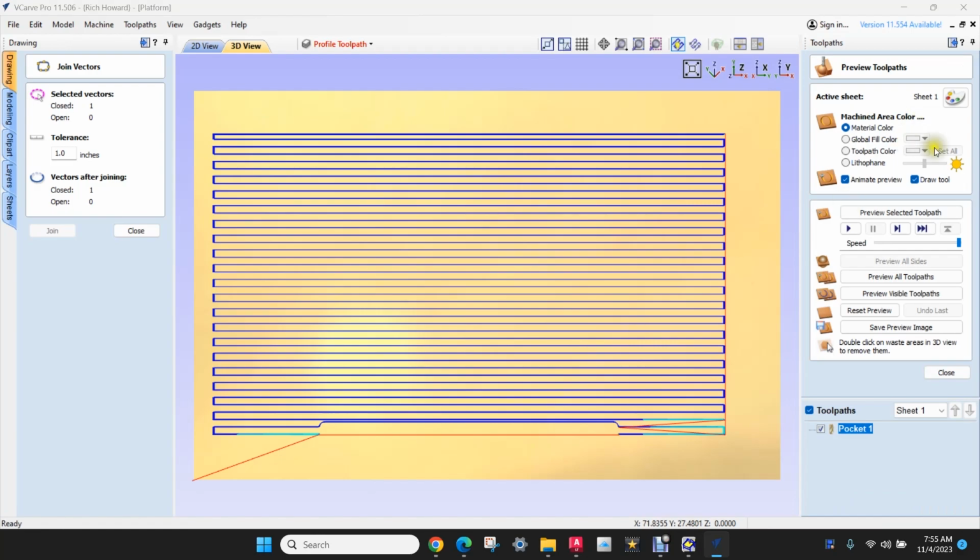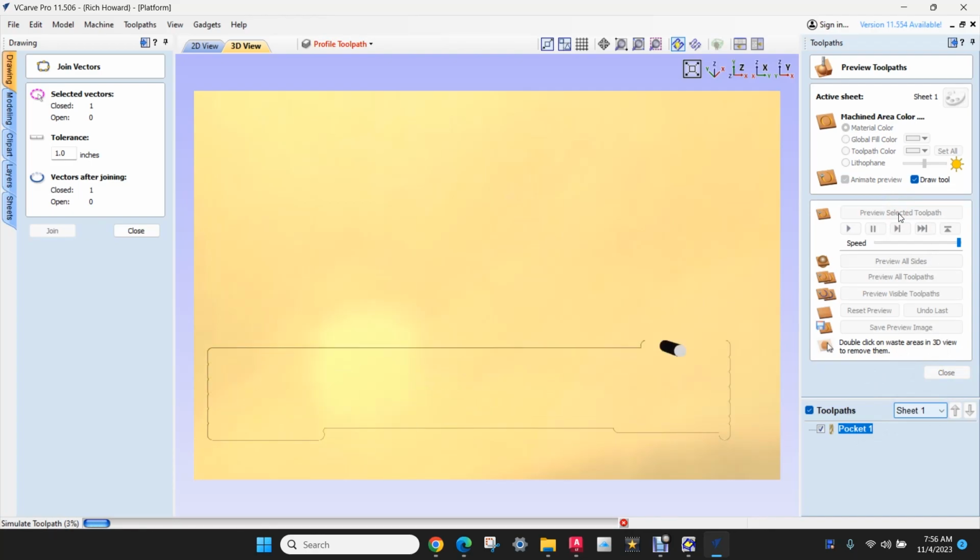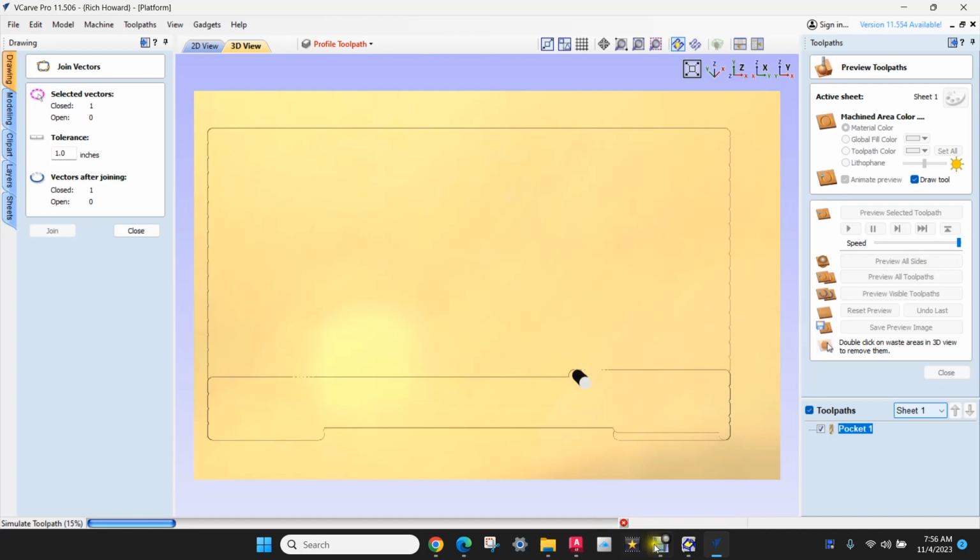Yeah, looks about right. It's going to take a month of Sundays, though, to cut this. Yeah, that makes sense. Our step over is leaving those small little artifacts out there. I believe that's why. And that's okay because, and I have this at full speed, that's why I extended the toolpath to get off of the workpiece completely at both ends. 65% of the way done.